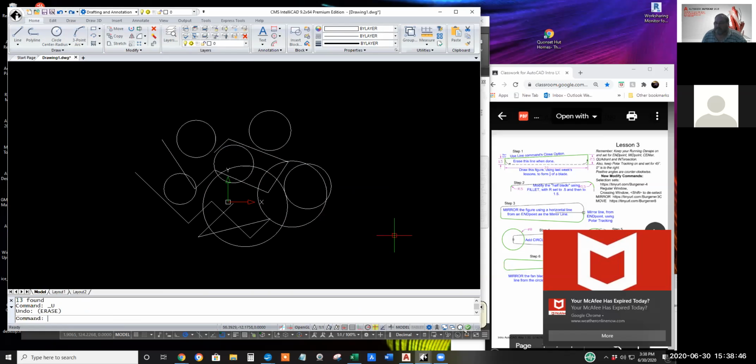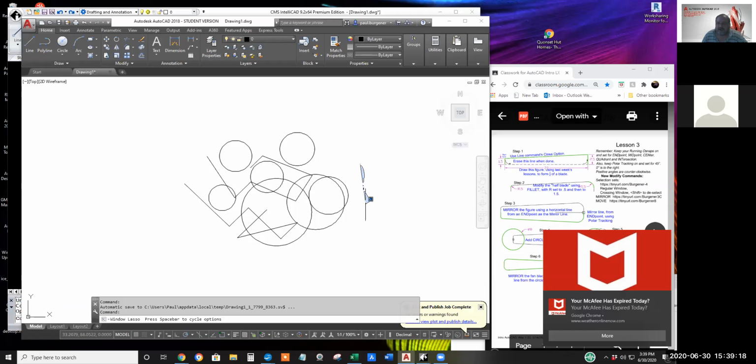Okay. Now, any textbook will tell you several other methods of selecting objects. I don't want to fire hose you, give you too much to learn, but P-enter selects the stuff that was previously selected. L-enter selects the last thing created. And students tend to like this. Okay, it isn't in IntelliCAD. AutoCAD's got this new lasso technique.